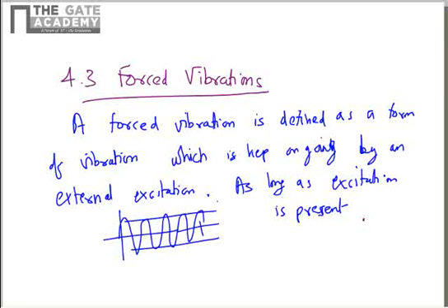But for understanding the basics, we'll consider sinusoidal forcing first, and that will give us insight into how a system behaves when it is subjected to external excitation or forced vibration. That theory can later be developed in much more detail for any general forcing function, because by Fourier series, any periodic function can be decomposed into components of sine and cosine waves.